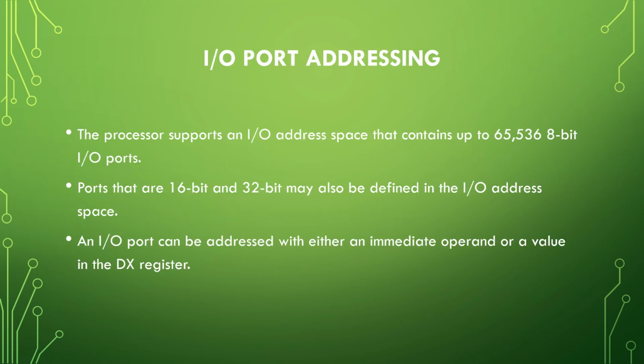I/O port addressing. The processor supports an I/O address space that contains up to 65536 8-bit I/O ports, and ports that are 16-bit and 32-bit may be defined in the I/O address space. An input-output port can be addressed with either an immediate operand or a value in the DX register.